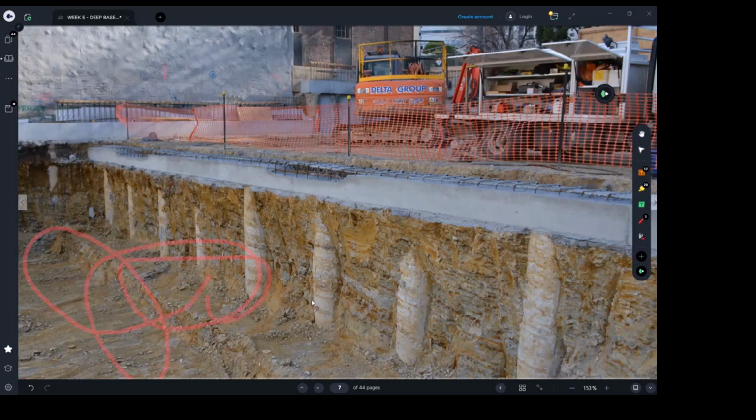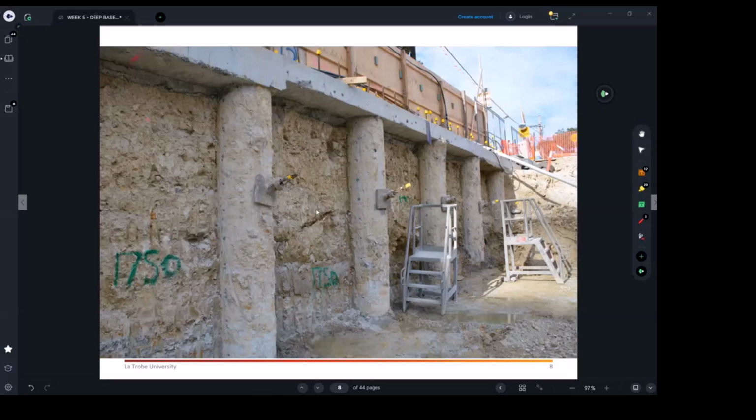Now we don't excavate the full basement 3 meters, it's still risky. We have to go typically halfway. So again, it's written in the structural drawings. They will tell you 1.5 meters down only. Then after we excavate 1.5 meters, we do this. What we do, we start, I think, yeah, that's what's happening here.